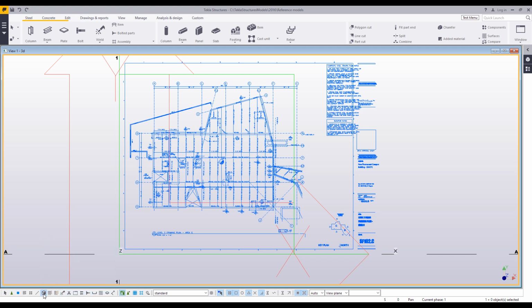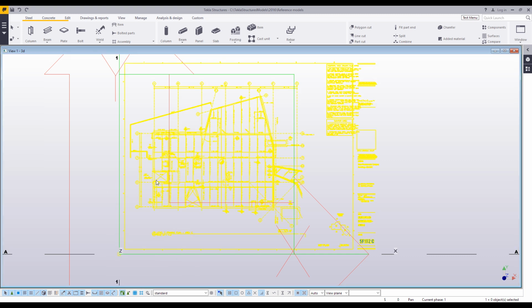You can either press it down, or as you can see, it pops up some of the other selection icons, so I don't always like to do that. A quick tip is if you hit F2, F2 either deselects all and selects all as far as your icons go. So a quick double tap on that, make sure that select reference models is pressed down, and so is most of the other things I'm going to need. So now that I have that, I can go ahead and scale this up.